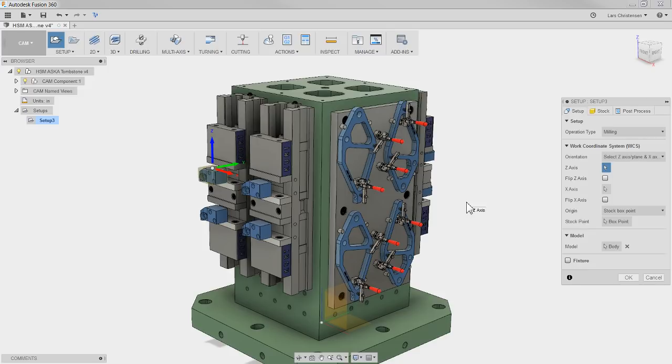That is kind of like the 4 degrees, right? The 4 sides. So the first thing I'm going to set is what is side 0. Now, that really depends on what you have out on your machine and how you decide to set it up. For this one here, just so we can get some B-axis rotation excitement, I am going to set this side here as side 0. And normally that is marked on your tombstone what that is and how you have modeled it up inside of Fusion.